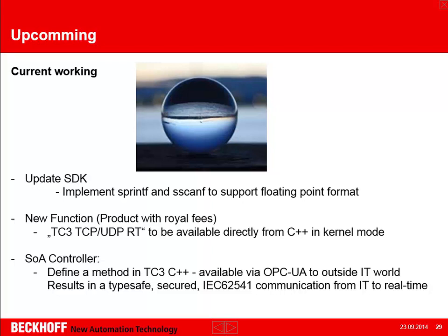And then, which is also pretty cool, I think, if you define a method in a C++ module, you can just activate a checkbox for that method call, and then this method call is automatically available in the OPC UA server on the same controller to the outside IT world.